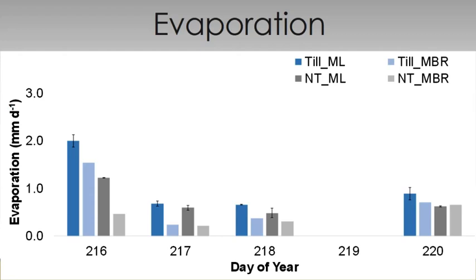We believe this accounts for the effect of tillage on the soil, affecting the surface structure and also a surface crust that could affect the resistance to evaporation at the till as opposed to the non-till soil surface. This would have caused higher evaporation on the first day, when evaporation is in stage 1 and believed to be more dependent on how much energy is being applied to the system.